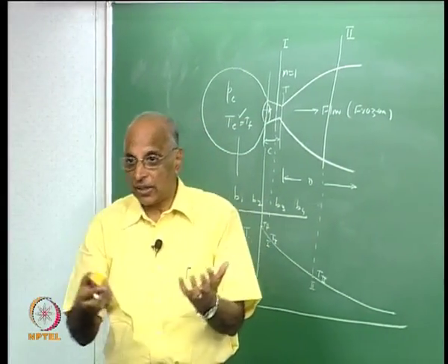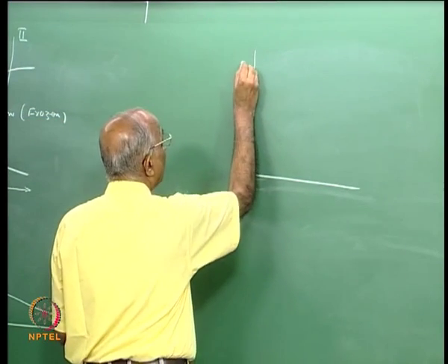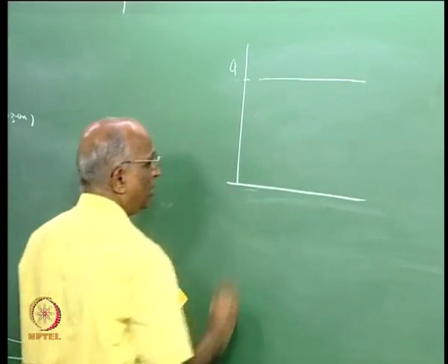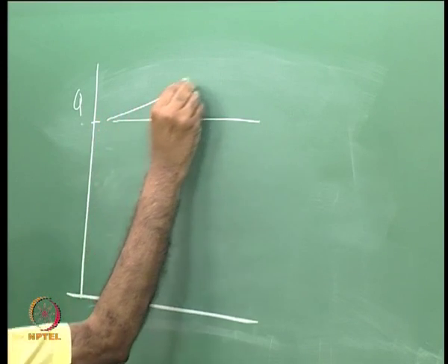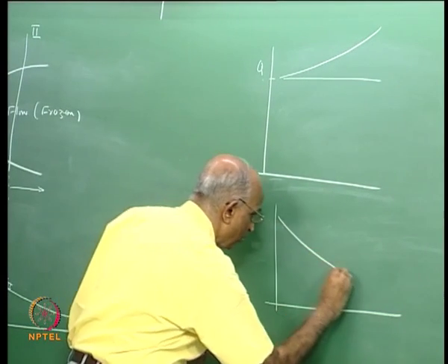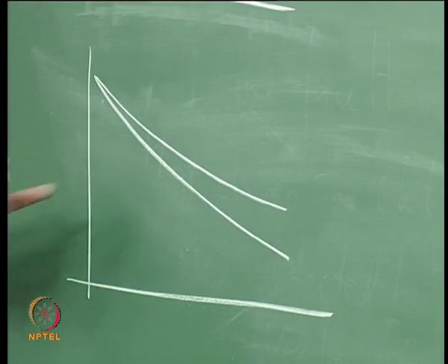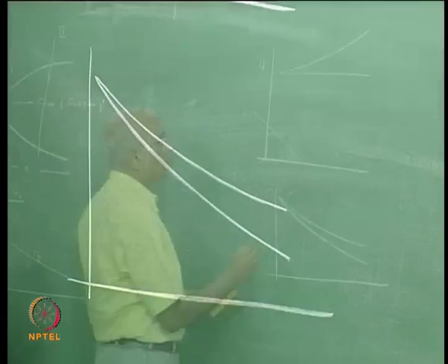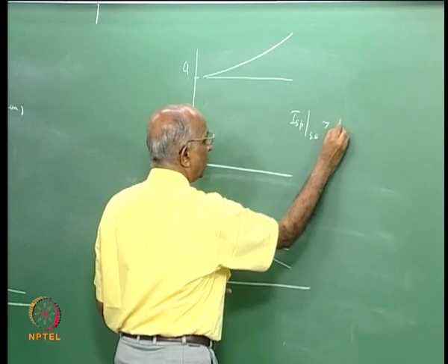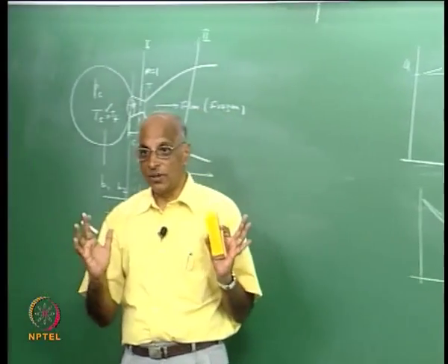And what happens in shifting equilibrium? Because the temperature drops I get more of the products which are not dissociated, because at low temperatures I cannot get dissociation, heat gets released. Therefore, if I were to plot my value of heat release, Q of the combustion, along the nozzle, I did not consider heat release at all. In practice Q gets released, and therefore whenever I calculated the temperature distribution in the nozzle based on expansion, the actual temperature will increase, and because the temperature has increased my specific impulse, ISP, corresponding to shifting equilibrium will be greater than ISP corresponding to equilibrium. Is this point clear? This is important.